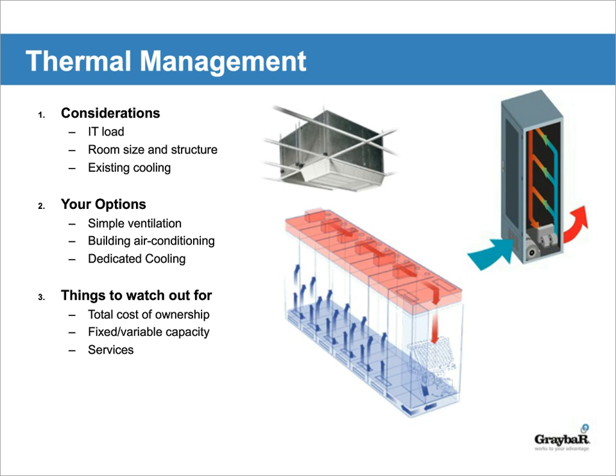You can go with those mini splits on the roof of your closet, or you can go with these self-contained solutions, right? Basically, this pod that you buy from vendors such as Emerson that have the cooling built into the cabinet. So on the right there, you see a cabinet with a built-in cooling. At the bottom there, you see a row with built-in cooling as well. So those are options that are available to you today. But again, it's going to depend on the amount of IT equipment you have. It's going to depend on the room that you have to work with.